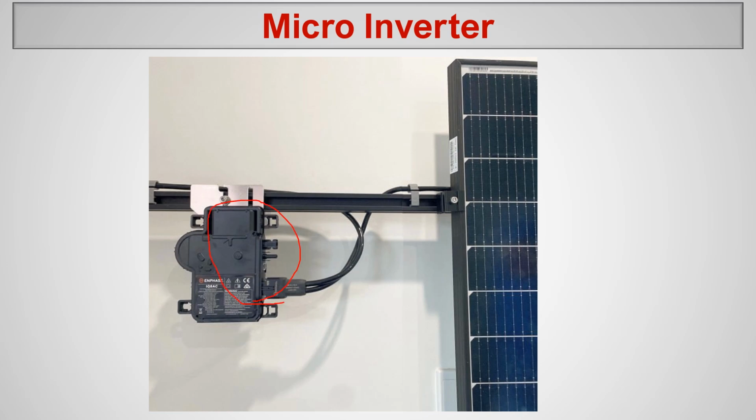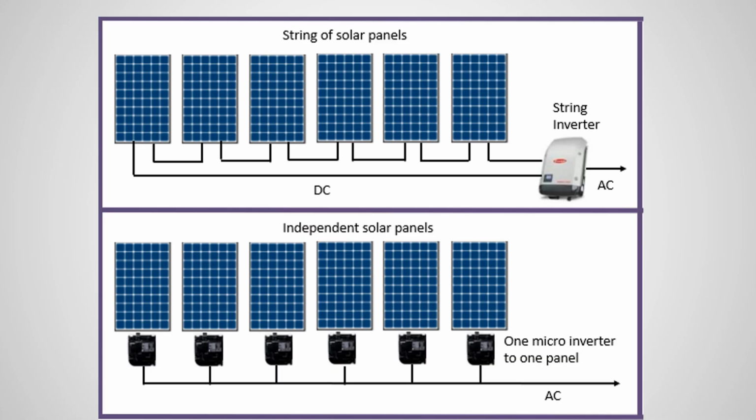So basically the microinverter will optimize, I mean it increases the total output, because each module is taken care of. Let's say one module is shaded, another module is not shaded. The shaded module will provide less current, and the unshaded module will provide more current. Both outputs are converted to AC, and the AC output will be added. So the shading issue is minimized in microinverters.